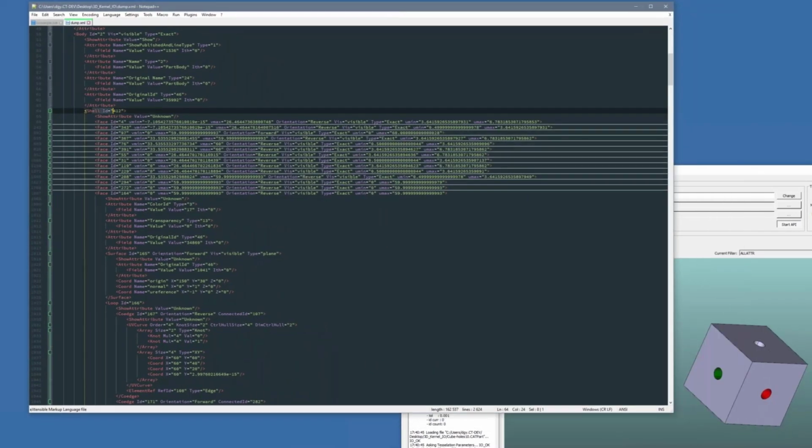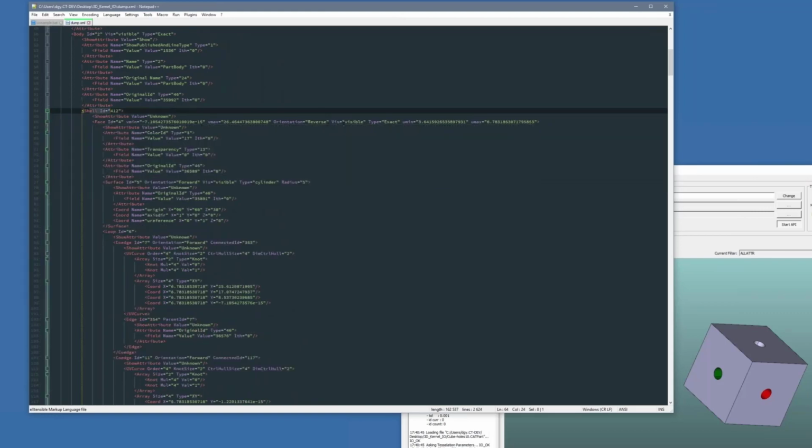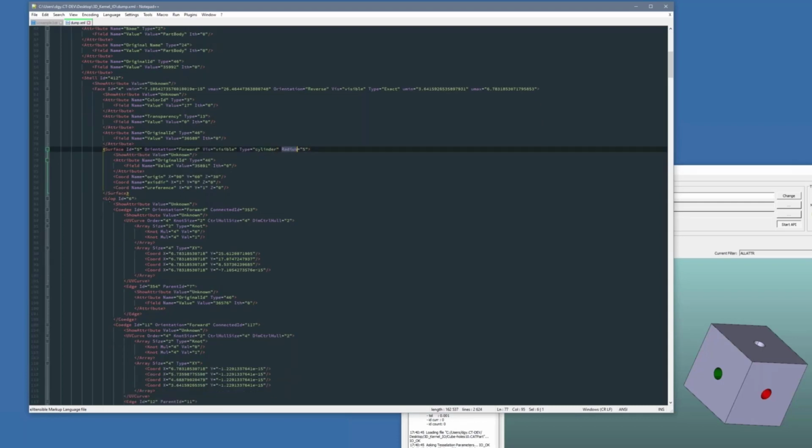Okay, etc. So for example, if I take the first face, it's an exact face, so it's not a triangulated face. If you load the JT file, it will be a triangulated face. It contains some attributes. It will contain the exact BREP data. So that means in that case, it's a cylinder. So it's one of the holes. You will get its axis, you will get its radius, etc. And you will get all the trimming co-edges.